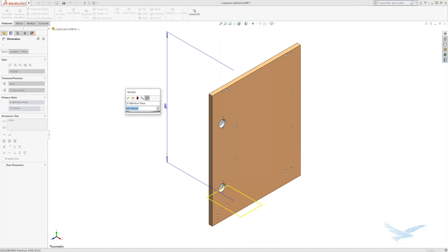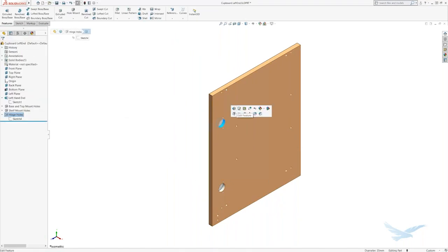So we'll manually go in, we'll change some of the dimensions inside that part. We're starting off here with the side part of that cupboard that we were looking at. And we'll go and change the height dimension to reflect the height it actually needs to be. And that might not just be a direct number that's on that spec sheet. It might be some kind of value that you're calculating as well. So maybe doing some multiplication, some addition, minusing a little gap because you know as the engineer that needs to happen. So you're building in design knowledge as you go through this manual process.